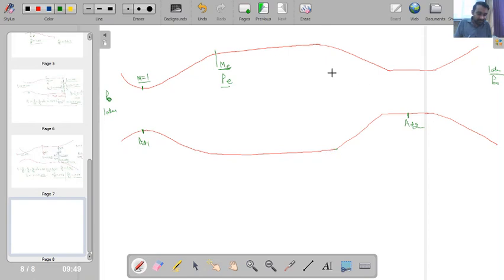Then here I have a supersonic situation. So in case of supersonic situation, if I decrease area, my Mach number will also decrease. I have selected this section such that once again at the second throat I am getting a Mach number of 1, and then after this I will be having a subsonic situation where there will be pressure recovery, and finally I will be able to reach 1 atmospheric condition and almost stagnant situation.